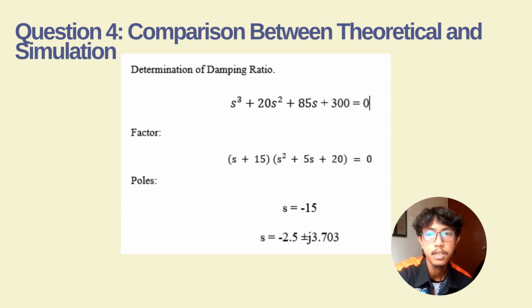But in reality, this is a third order system with an extra pole at s equals negative 15. Even though that pole is far to the left, it still exerts a subtle pull on the transient curve, shifting our peak time and increasing the settling time and overshoot in the actual simulation. Ultimately, the simulation validated that our second order math can be reliable.